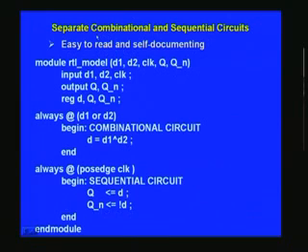We mentioned earlier that we need to separate out combinational as well as sequential circuits, and here it gives one particular module. A module you can regard as a single file in which you need to follow a certain pattern while coding it. What we have seen earlier was only piecemeal coding, and now it gives a little more information. The code that you are going to put is a module. A module is something like a black box. You have a block diagram which you are already familiar with. It will have IOs, and that's precisely what you have here. So that block can be given a particular name, and the block itself we call a module.